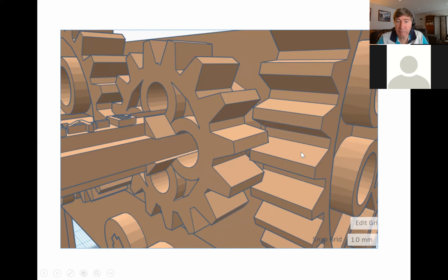This part of the gear might as well not even be there. It's not touching anything. And same thing with the small gear. This part, the left side of the tooth here, isn't doing anything. So all of our forces are acting right here. And it'll work. But over time, what's going to happen is that our teeth are going to start wearing funny. We're going to get a lot of wear right here, and no wear right here, and our teeth are going to get deformed, and over time a reliability problem is going to arise.